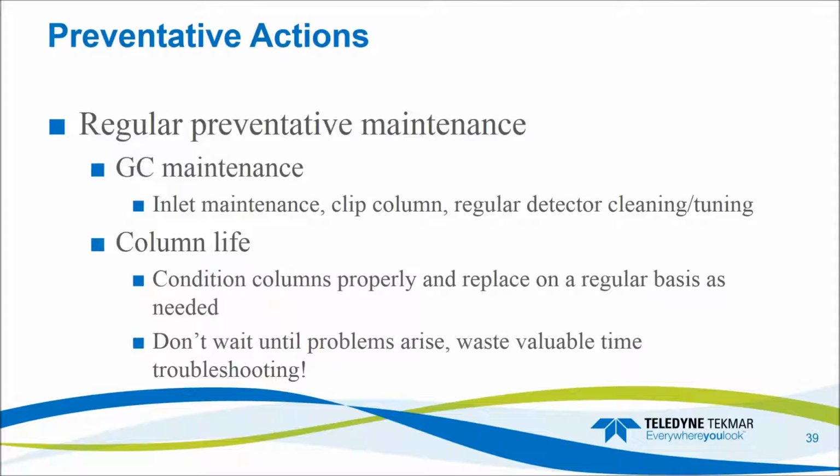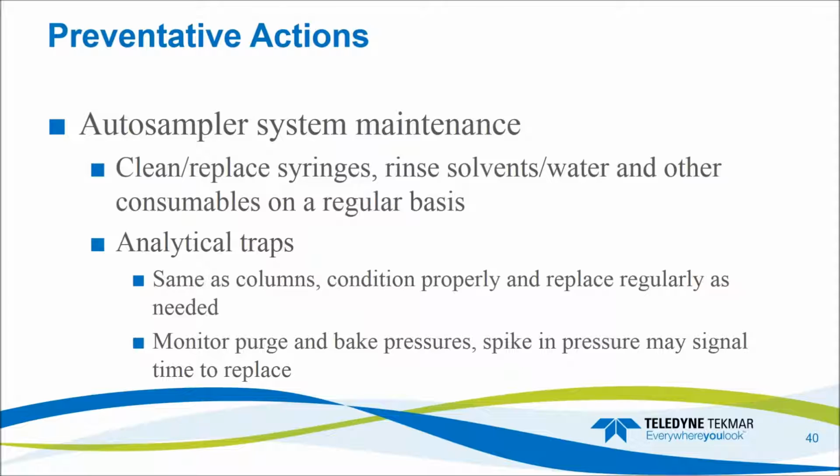You really should know where your column is in its lifespan and what kind of issues you'll start to see that suggest it should be replaced. And if you wait too long to replace your column and you start to have these types of problems arise, you can waste valuable time on troubleshooting when in reality it's that your column is old and exhausted, and you could account for that.